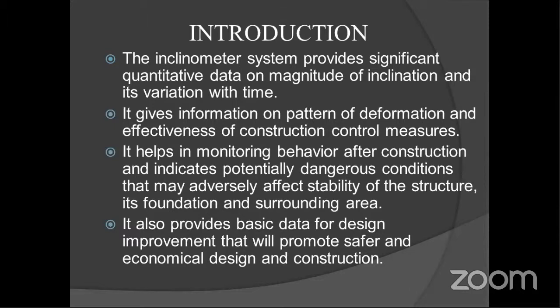The best part of this inclinometer is it will give the maximum, sorry, the minimum deflections; its least count is 0.1 mm. So we can come to know how accurate it is.